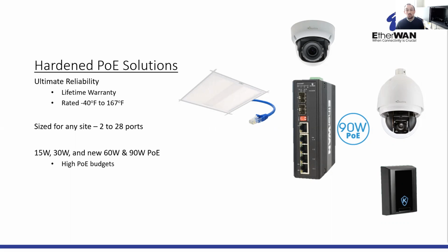And something I think is really cool is, let's say we've got a non-PoE device that wasn't designed for PoE because 90 watts is the brand new standard. There just traditionally hasn't been enough power for whatever that class of device is. Well, we can take this 90 watts and use a splitter. I can take that 90 watts and split it off so that I have 12 volt DC or 16, 24, or 48 at different amperages and a standard network jack.